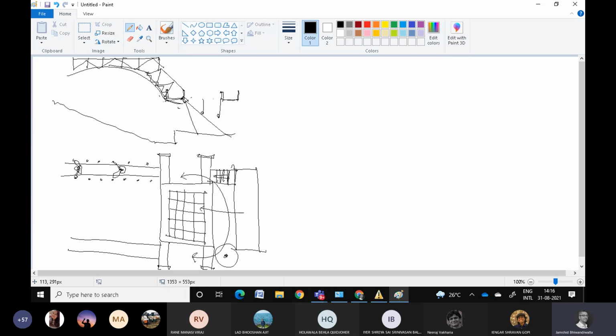Okay. So you place the catwalks preferably only where your light positions are, and no sooner than later, as you must have seen, the portfolio is going to expect you to have an electrical layout. So do not have the catwalk anywhere and everywhere. Have the catwalk only based on the kind of lights you have. Suppose your lights are all focused towards the corners, then make sure that your catwalk is there only in the corner and does not run along the center. So make sure that you have limited catwalks, maximum 2 to 3. Suppose you have lights in the center, you may have a catwalk that is there in the center.